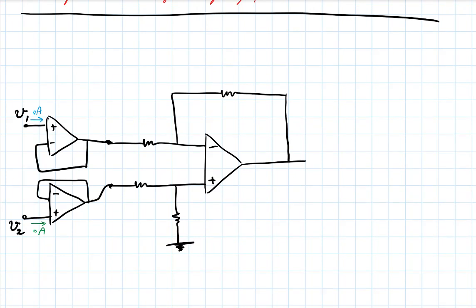So the voltage followers here have provided an isolation, a degree of separation between whatever you are going to connect at the input and whatever was required here, which was something. And here, something else. Those are now provided by these input stage op-amps.